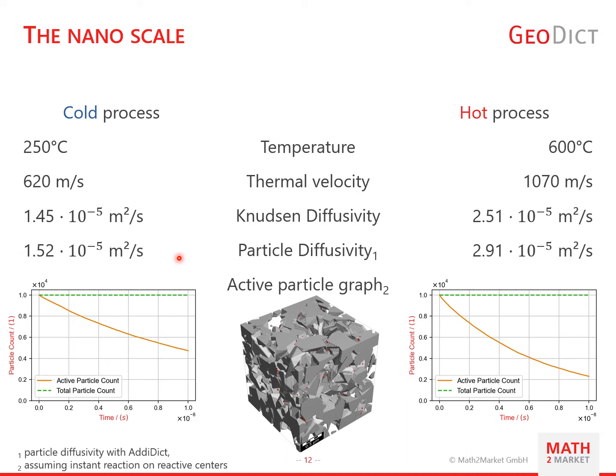As you can see, the particle and Knudsen diffusivity is rather similar in this structure, and this is the case because we are now near the Knudsen regime and our Knudsen number is more or less 1. So both values are very similar here.